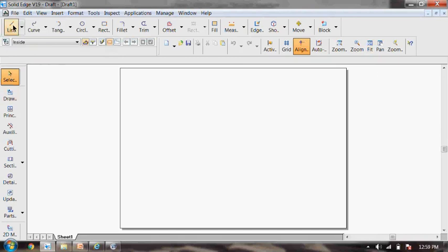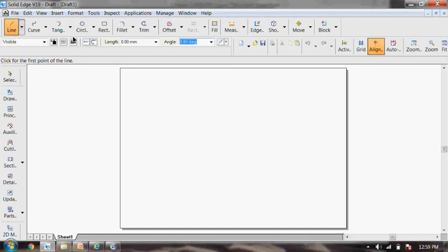So to start with, first we will go for construction of a line. Click on the line command. Take the thickness as 0.13. So construct a line, the XY line, and then use the text command. Where do you find the text command? You find it in the drawing view bar. This is the drawing view bar.